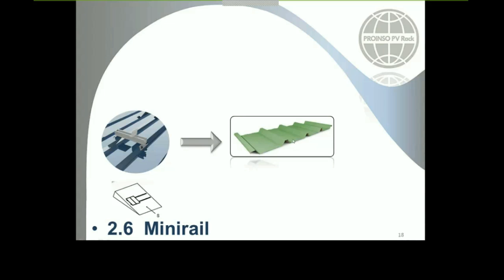One thing that we have to take into consideration is the thickness of this roof. Why? Because the less thickness it has, obviously the weaker the roof is. So we have to ensure that it is more than, I think, 2 millimeters, and that, given the loads that we are going to transfer to this roof, the sheet can support it.